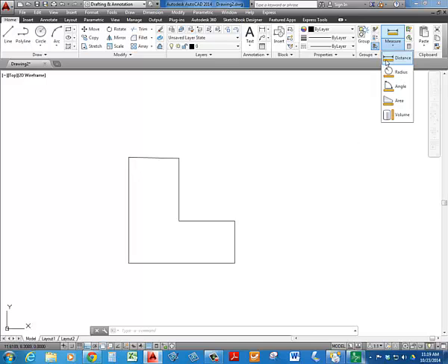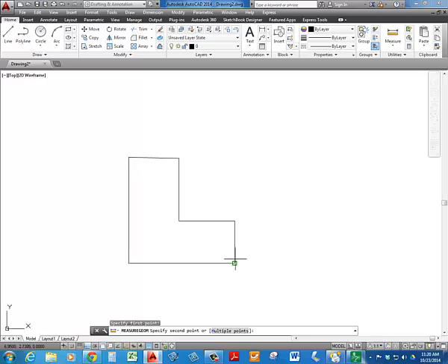Okay, so you can just click on distance. You have to have some snap turned on. Your O snap for endpoint should be on as a minimum, if that's what you want to check. And you click 2 points, and then it gives you, well, what do you know? It kind of looks like the list command. Alright?